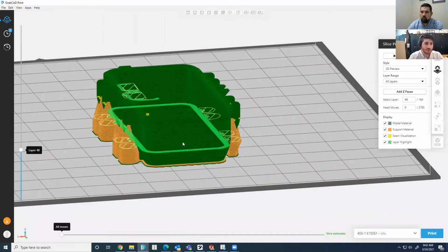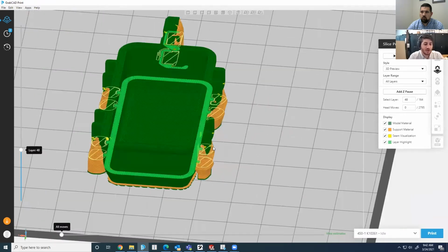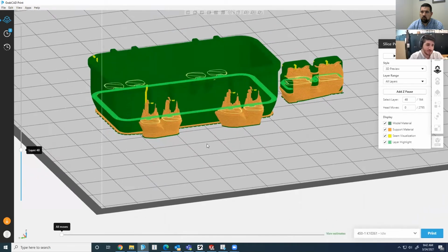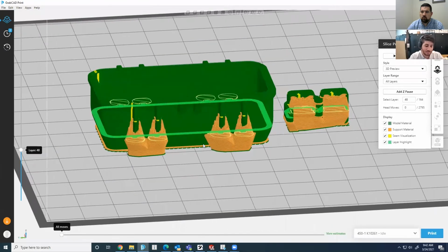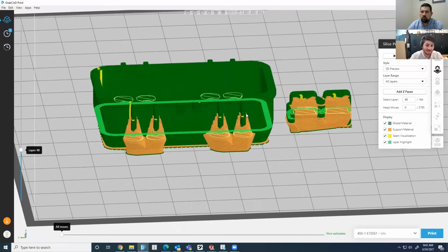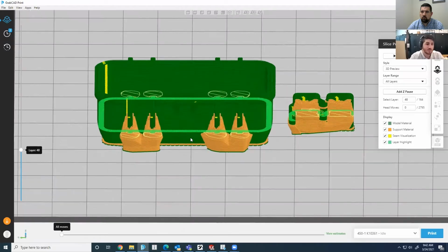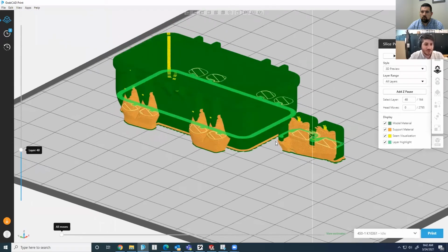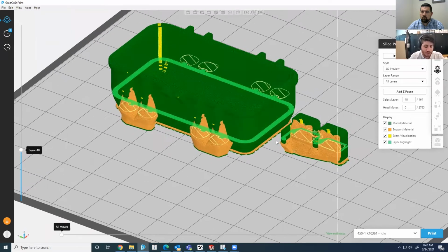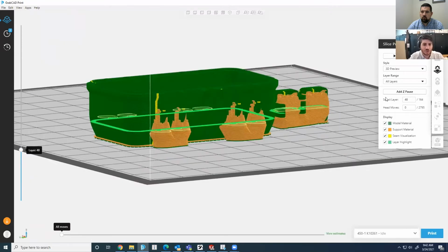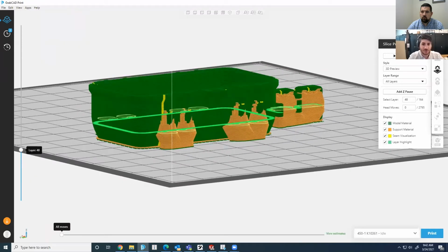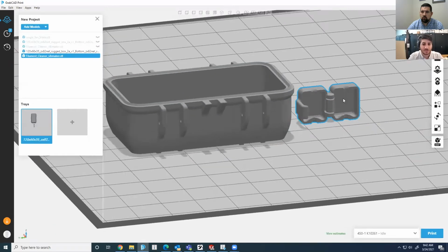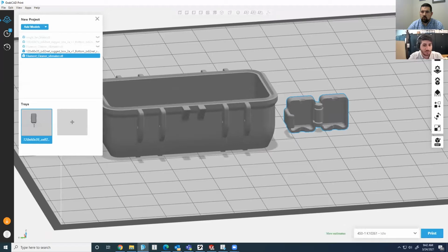But most people, you're going to take it off the build tray on the machine, take off as much as you can, put it into your post-processing unit, and then let it sit for about an hour, 45 minutes to 2 hours, take it out, put it in some fresh, clean water, let it rinse off all that sodium hydroxide. It was really just a strong soap, and then wash it off and let it dry, and then you have your nice parts.